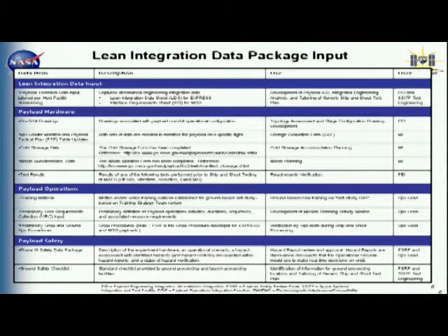Let's see, key environmental tests such as off-gas testing, vibration, acoustics, EMI, and EMC. You can have those things conducted prior to Gate 3, and that's probably a good idea. But if you do have them done prior to Gate 3, go ahead and turn in those results.